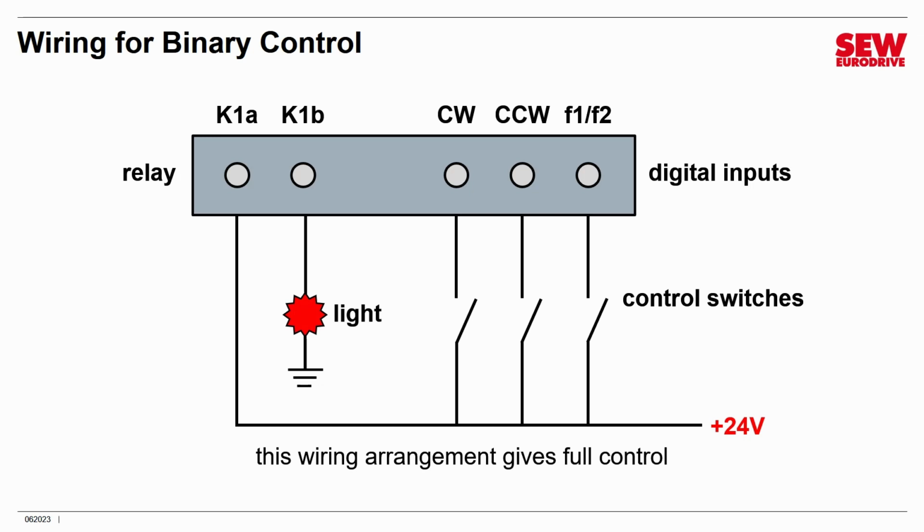Remember, this is a low voltage relay contact. Do not connect it to 120 volts AC or anything high like that because you will damage it. It's meant for low voltage DC.